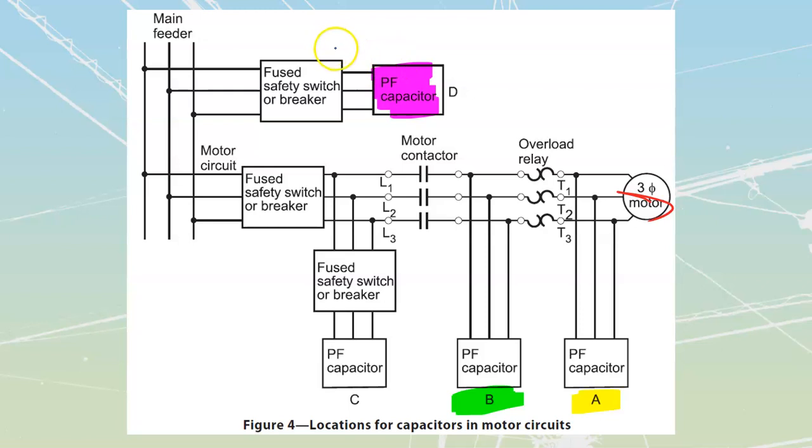So this power factor correction capacitor is made up of many small ones that is going to be monitoring my mains over here. We'll stick a couple of ammeters around those, and then it is going to be switching on and off through little contactors inside of here, multiple different capacitors as they're needed to power factor correct for the system.